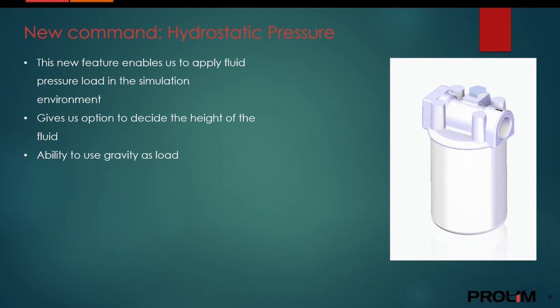First, we will look at the new command called the hydrostatic pressure, which has been introduced in the software. This new command helps us to apply the fluid pressure in a simulation environment, which was not an option in the previous versions. It also gives us an option to decide the height of the fluid, and we also have the option to use gravity as a load. So we will just quickly demonstrate how to do this.